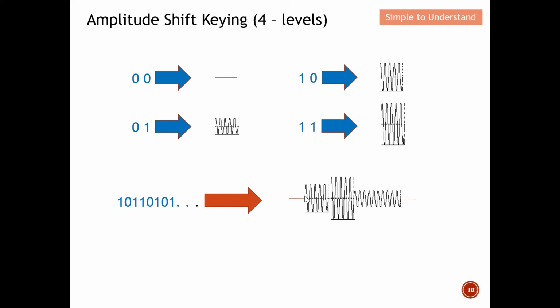In short, this is the same amount of data that I want to send. Based on the waveform over here, you can see that this waveform means that a message 10 is being sent over. This one has the largest amplitude, so therefore I know that this is message 11. And these two having the smaller amplitude mean that the message is 01. Can you see over here again? The message can easily indicate the input value of the digital signal.